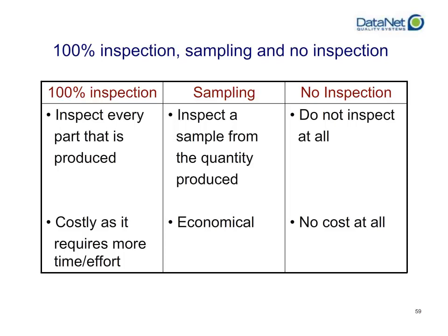The problem with 100% inspection is that it is very expensive. It requires time to measure everything. It requires effort to fix anything. It is a very expensive process. Now, in certain regulatory situations, you may not have a choice. This is your only option. But if you're doing destructive testing, this isn't even an option at all. You can't do it, because if you have to do tensile testing and you do 100% inspection, you've literally broken everything that you are trying to sell or produce.